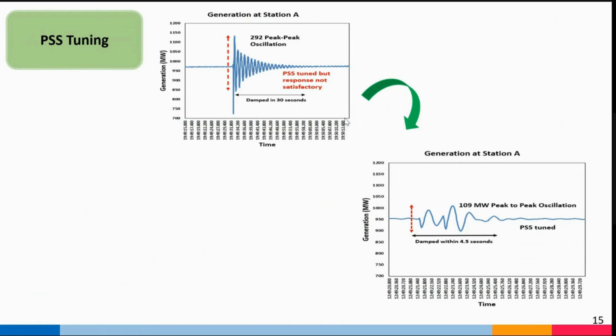As I already informed you, each of the power plants' outgoing lines is monitored through synchrophasors. So I am able to monitor how much active power generation they are injecting into the system. If you do any kind of test at that plant, whatever transient or variation in active power there will be, it will be easily captured through the PMU devices.